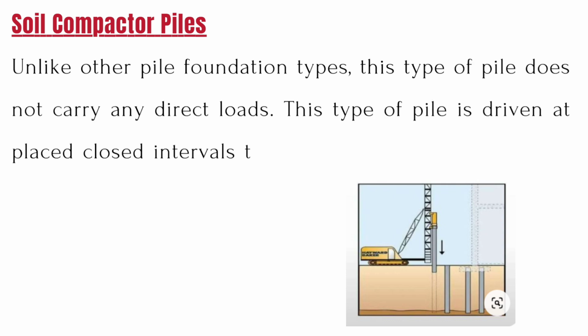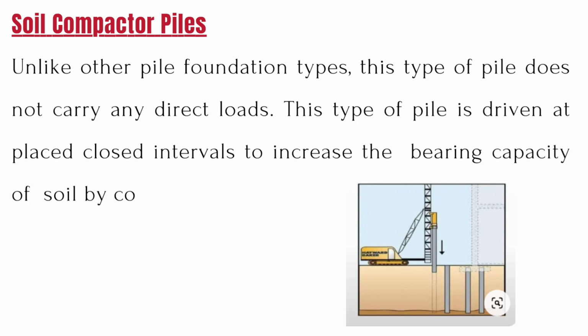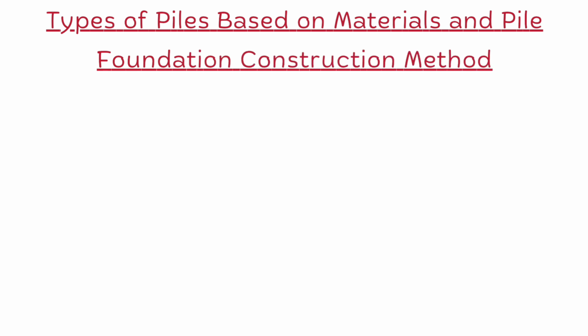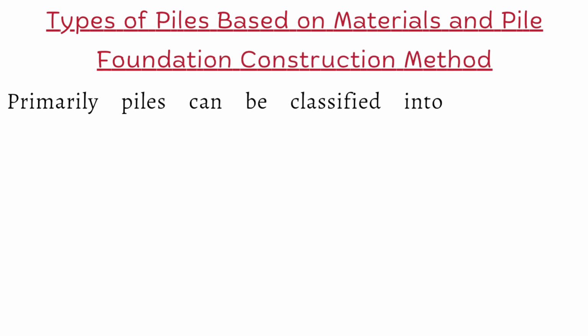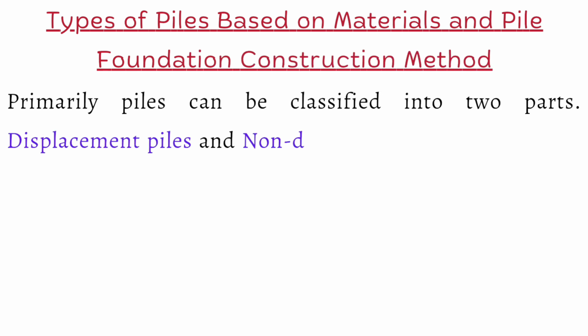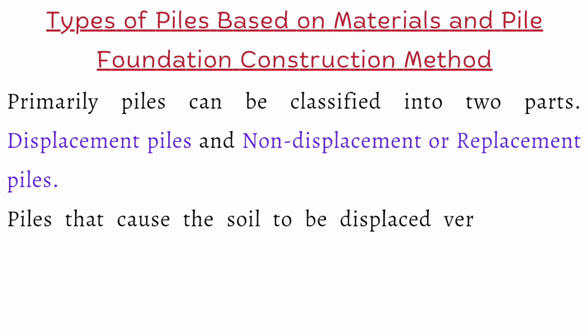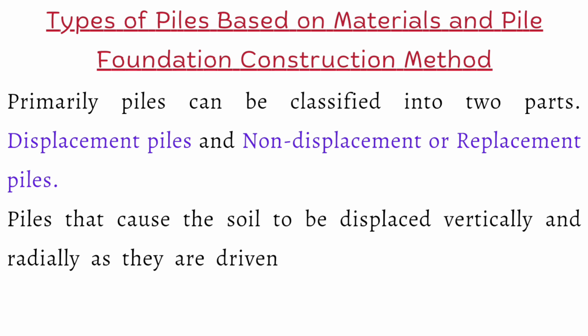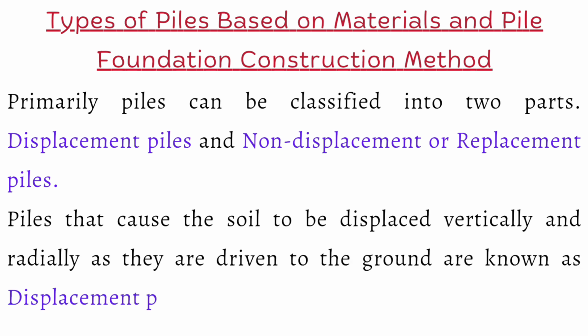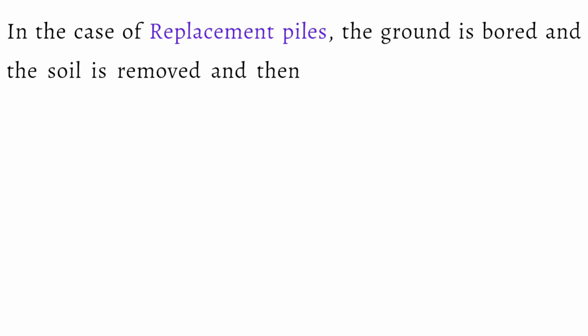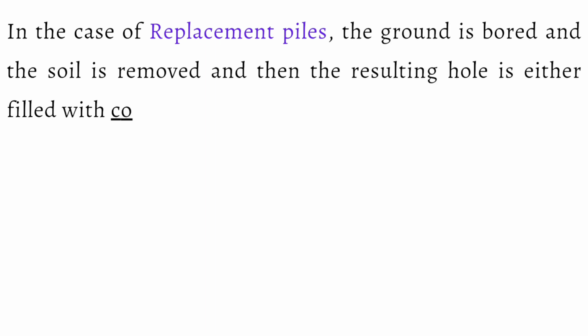Friction pile. The friction pile transfers the load from the structure to the soil by the frictional force between the surface of the pile and the soil surrounding the pile, such as stiff clay, sandy clay, etc. Friction can be developed for the entire length of the pile or a definite length of the pile depending on the strata of the soil. In friction piles, generally the entire surface of the pile works to transfer the load from the structure to the soil. The surface area of the pile multiplied by the safe friction force developed per unit area determines the capacity of the pile.